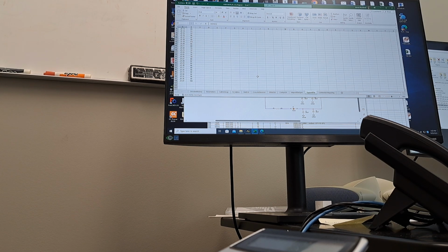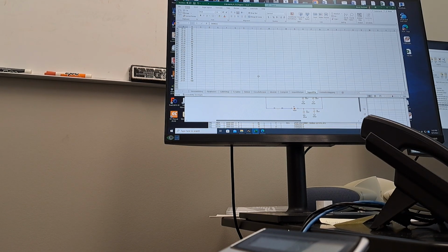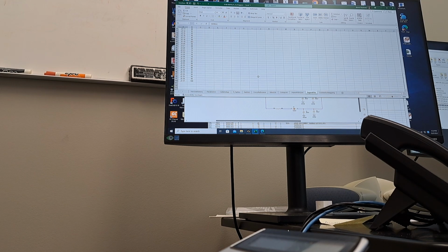So what they're supposed to do in test is, if it says open, they take their DMM and make sure that those pins are in fact shorted together. That's what they're supposed to do with every open. And then if there's a short, you have to go on the board and try and troubleshoot it and find out where it is.